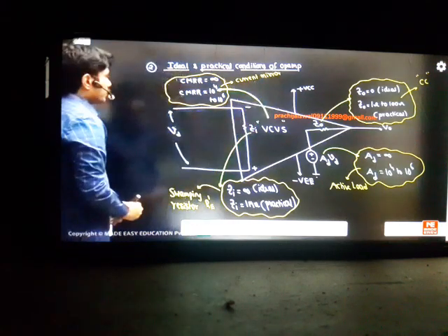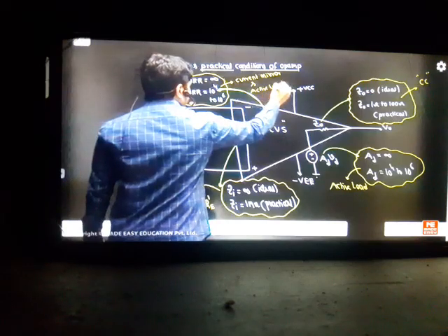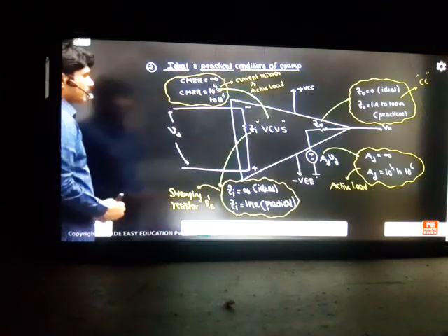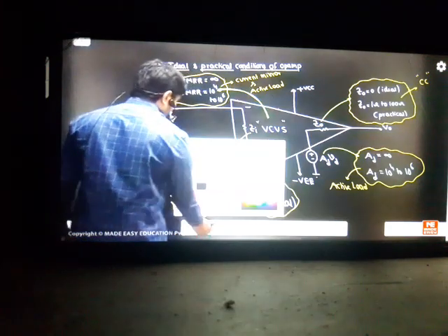Current mirror helps me to reduce the common-mode gain, and not only that, active load also indirectly helps me to increase the AD. So both techniques will help me to increase the CMRR. These are the points we learned in the previous module. And the last one is offset.